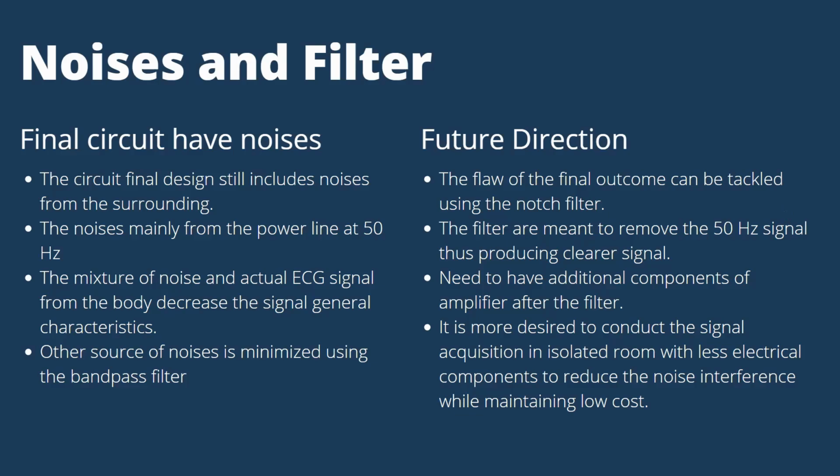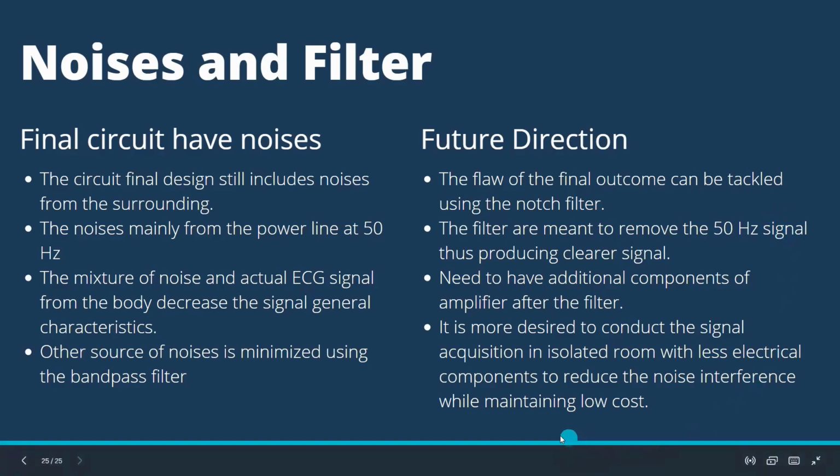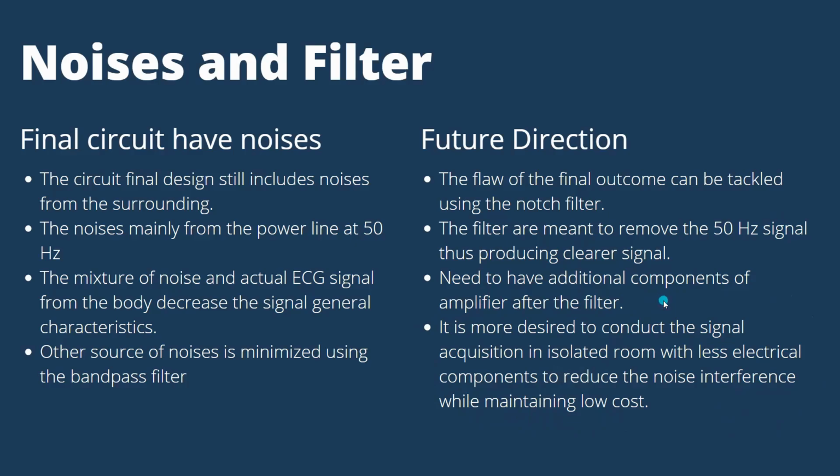We try to make the circuit able to work with less noise. In this case, the problem is noise, so we focus on less noise. Therefore, I think it is better if we can just provide a room with fewer electronic appliances or working devices, so that the chance of noise mixing with the ECG signal from the subject or the patient is reduced, rather than producing more and more filters and amplifiers.